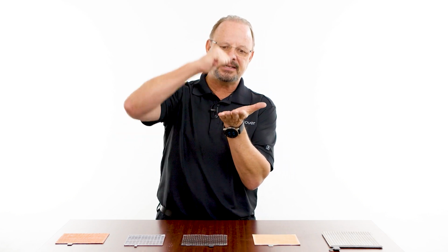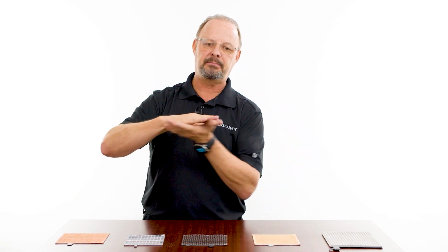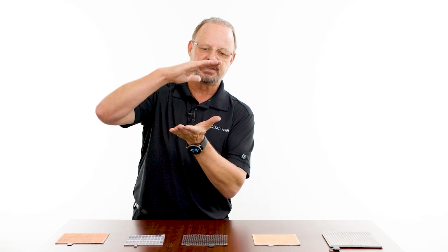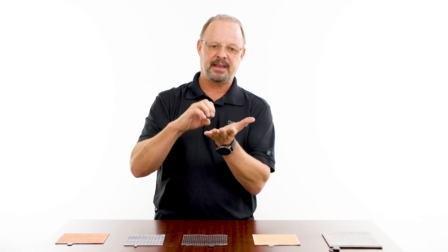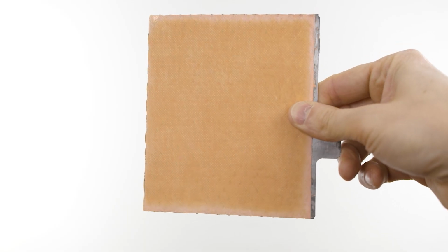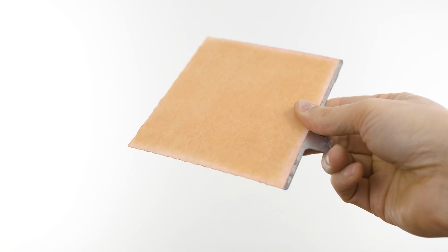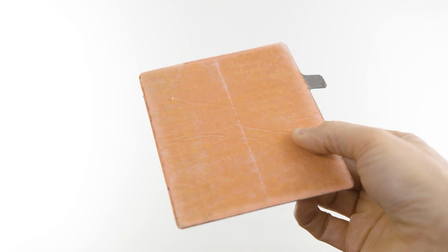In the battery production process, it's about hundreds of meters a minute of these plates running through the production process. So think of what type of plate would actually grab the paste best when the plate is being pasted, when it's moving at really high speed through the pasting machine after the grid has been formed. If you're going to go at a really high speed, the odds are you don't want a plate that has high tensile strength, because it's just not going to work very well. Particularly if that paste is going to be a drier paste, like what we might use in a deep cycle battery, versus a wetter paste, like what we might use in a starting battery.